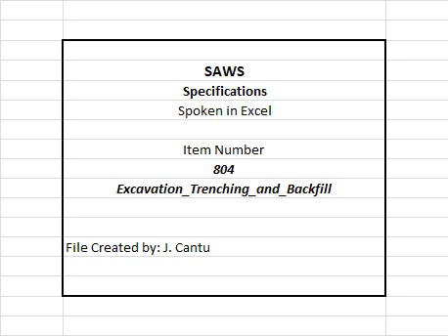Where specified by engineer, only the secondary backfilling may incorporate native excavated materials approved by engineer for backfilling, consisting of earth, loam, sandy clay, sand, and gravel, soft shale or other approved materials, free from large clods of earth or stones. Where pipe is specially coated or sleeve/tape wrapped for protection against corrosion, care shall be taken not to damage the coating or sleeve/tape wrap. Damaged wrap will be replaced at contractor's expense.